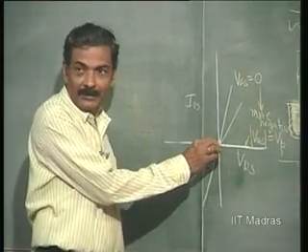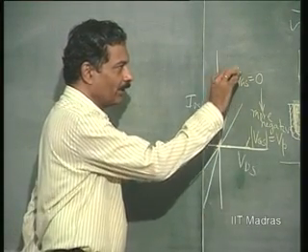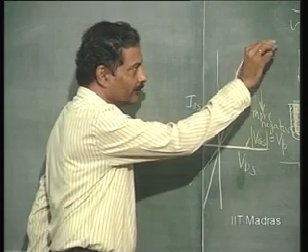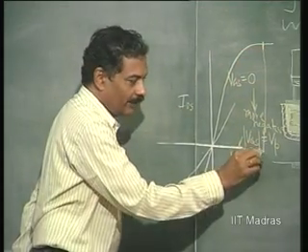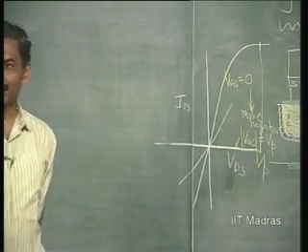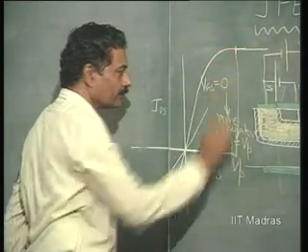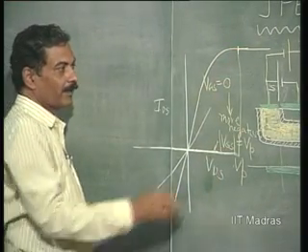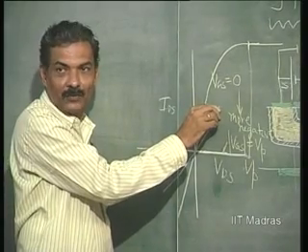The same thing happens, this is a nonlinear resistor here, and this will keep on decreasing, and at a value which is equal to what? VDS equal to pinch off, it goes to saturation, the current remains constant. And let us say this corresponds to VGS equal to minus 1 volt.